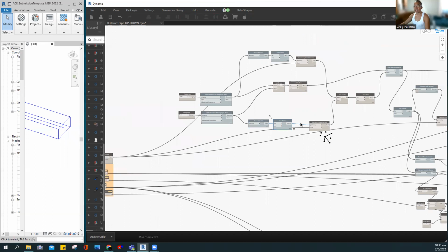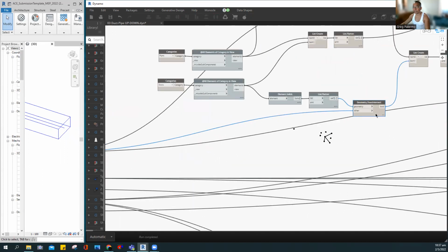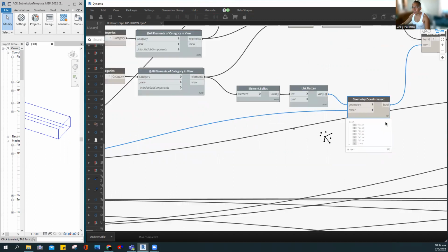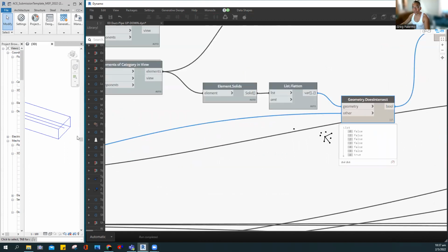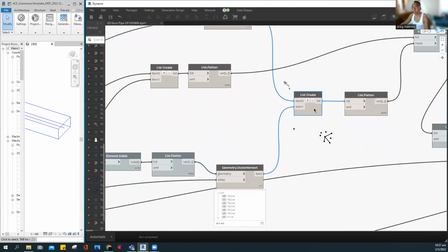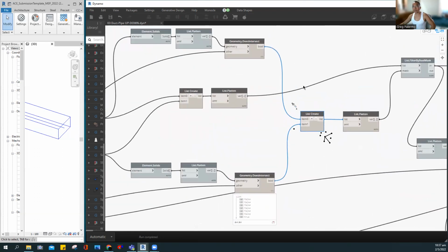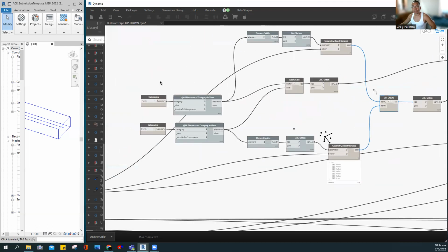Okay, then after that, you intersect, which gives a Boolean value. So select here the point, intersect with the solid, the geometry here. So we have a true value, correct? Because we selected the points here. Then after that, you combine the list of this value and the list of this value. Why do we combine it? Because what if we select the pipes?